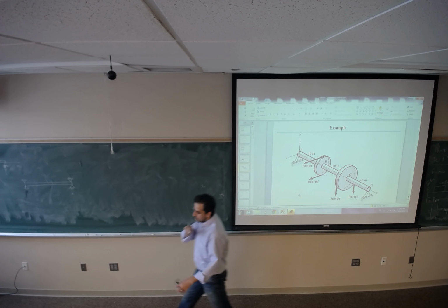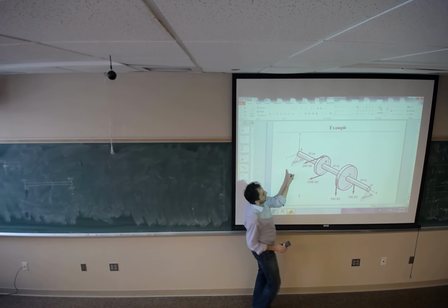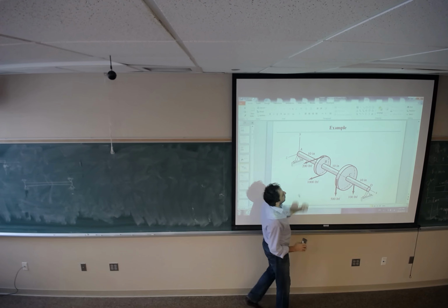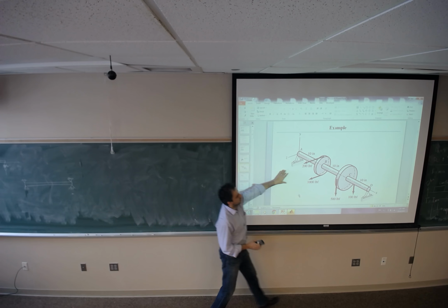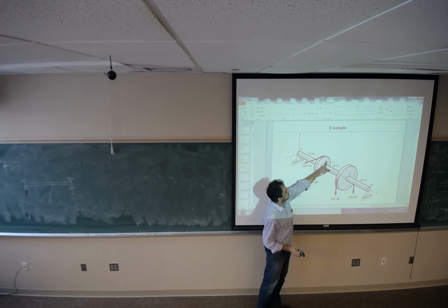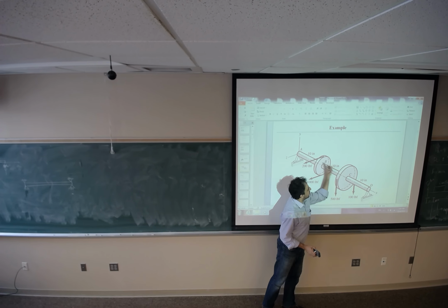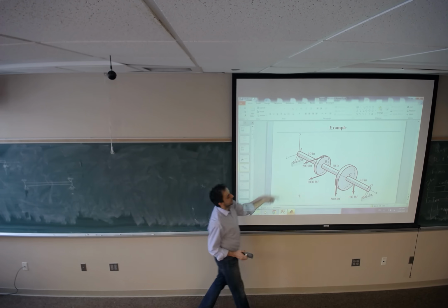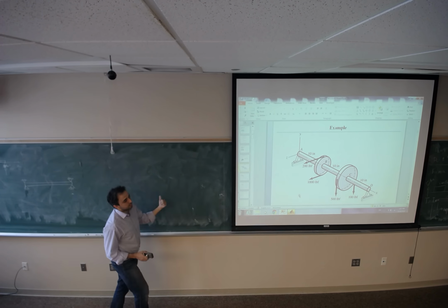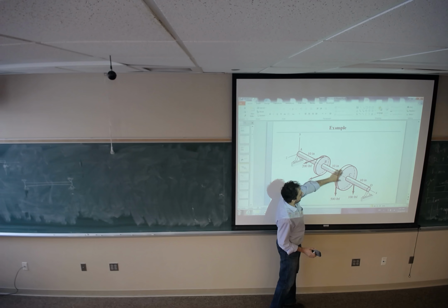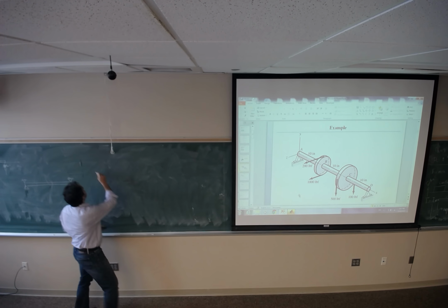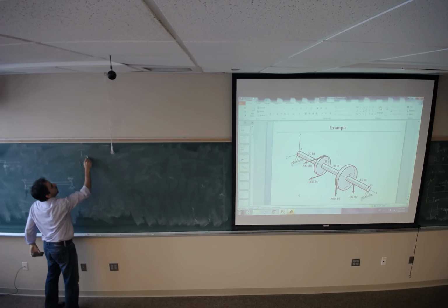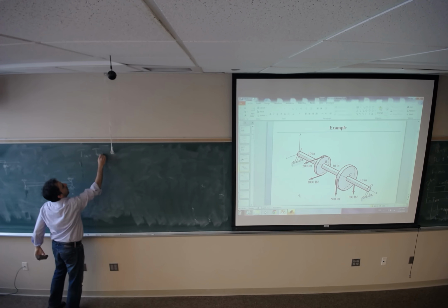Now back to this problem. The motor is going to have the input torque. The torque is coming through this pulley, and we know that this driving shaft is rotating at constant speed. It tells me whatever torque is coming into the shaft should go out at pulley C. So T in should be equal to T out.